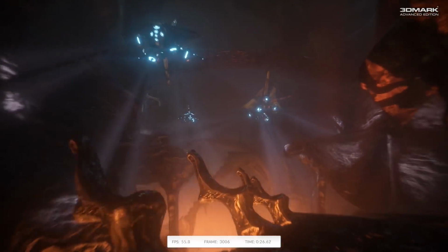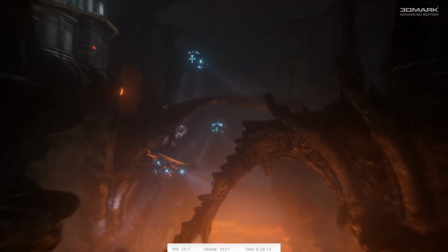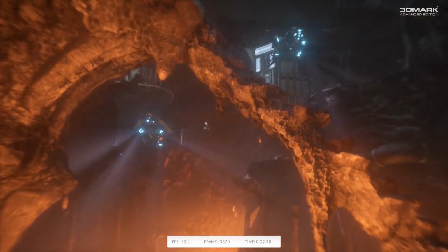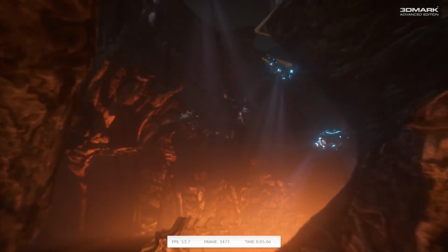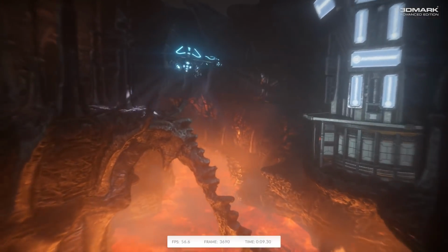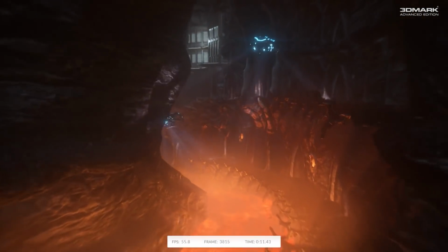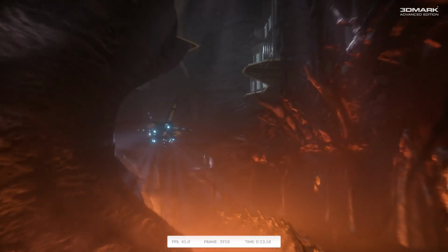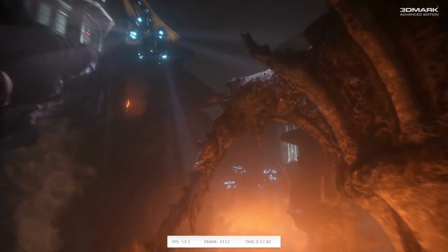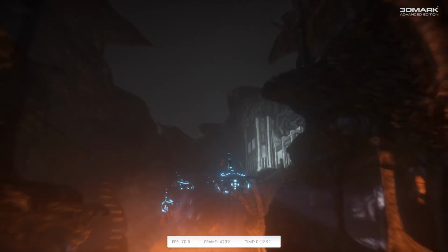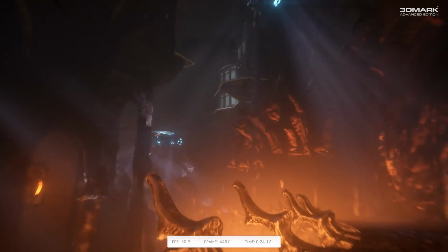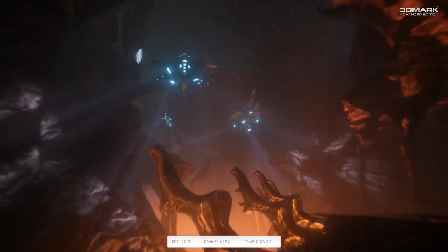With stock settings inside of Wattman, if I run this particular test, I will get 87% thereabouts, which is a failing score. The reason is that the card will just go balls to the wall. It'll try to hit those higher clock speeds. It will thermal throttle and back off, and as the card gets hotter, it stops hitting those higher clock speeds as regularly as it was at the beginning of the test. The way that score is computed is it looks at each of those 20 runs.